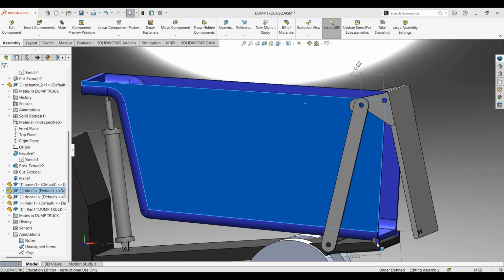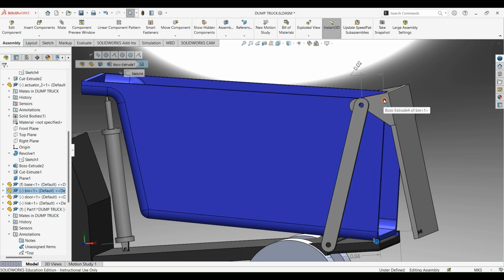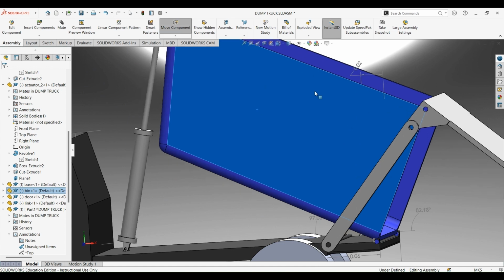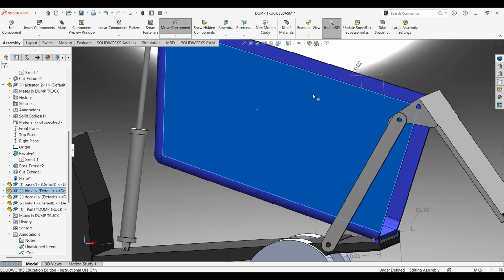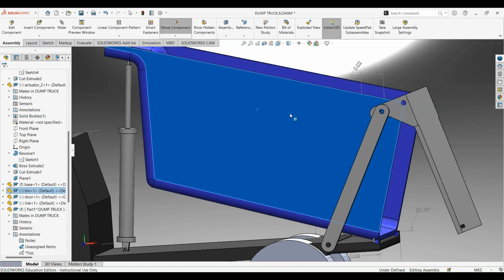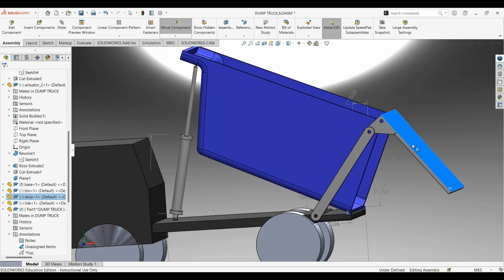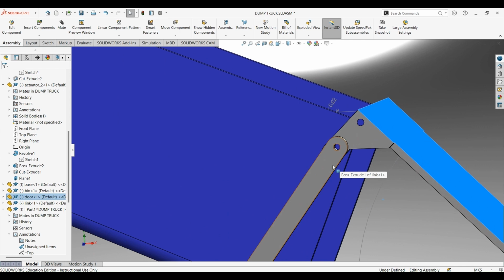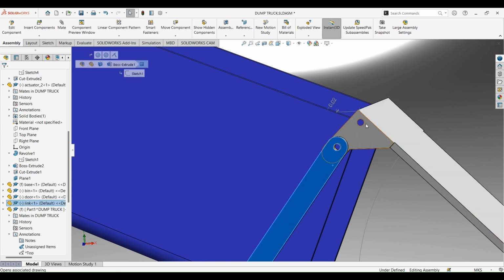An interesting observation is that it is possible for these 4 links to satisfy the Grashof criterion. However, that would result in an unwanted motion beyond the desired range of the door, as this smallest link would then become a crank. To avoid this, a constraint has been set on its range of motion, which limits this link from getting inverted beyond the maximum range. The extreme position is thus almost a dead center configuration, where these links become collinear with an uncertainty regarding the direction of further motion.